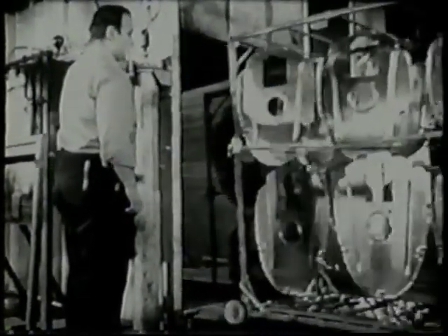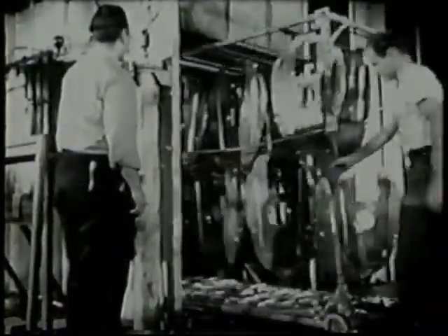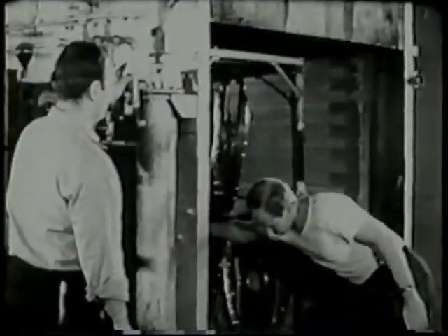After the furnace has been heated up to heat treating temperature, it is ready for loading. The furnace door is raised pneumatically or hydraulically. The rack containing the alloy parts is rolled into the furnace, and the furnace door is lowered as quickly as possible.